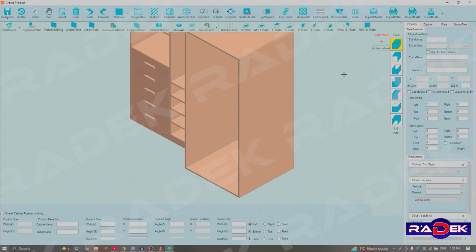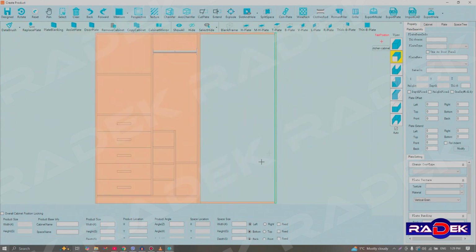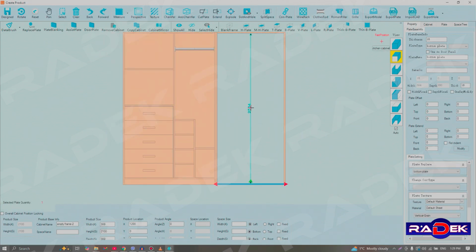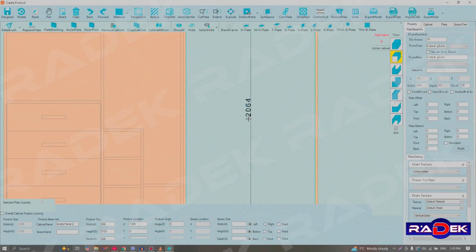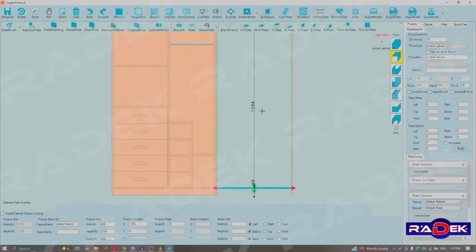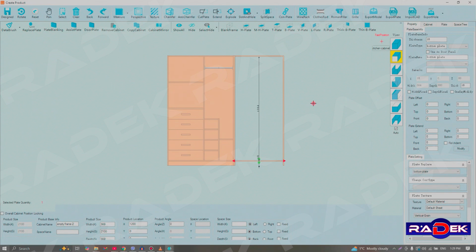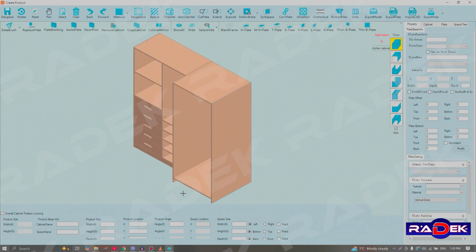The software displays the dimension lines, which we can edit directly. We click on the current value of 2064 millimeters and subtract 80 millimeters, resulting in 1984 millimeters if my math is correct. After confirming the change, the software moves the panel upwards, creating a new empty space below it with a height of 80 millimeters. Before adding the support elements, we switch back to the default view and then select the upper empty frame and begin adding the components.